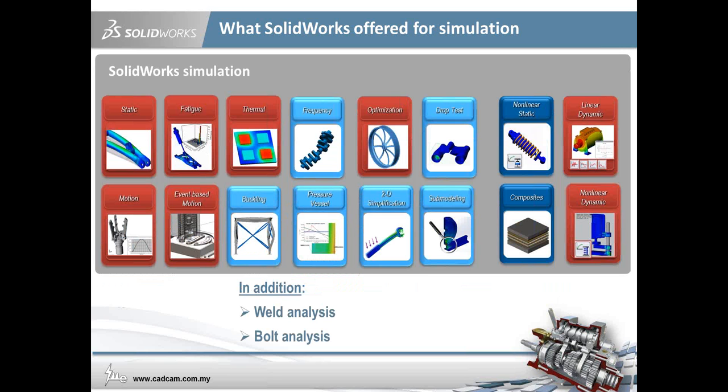This means what you have seen just now in the video for the finite element analysis. That is the static analysis. And then fatigue analysis. Let's say you want to design your part for warranty. Let's say I want the parts to be available to use over 10 million cycles, and you do not want it to fail if the operation is less than 10 million cycles. Then we can use a fatigue analysis to study how durable our design is.